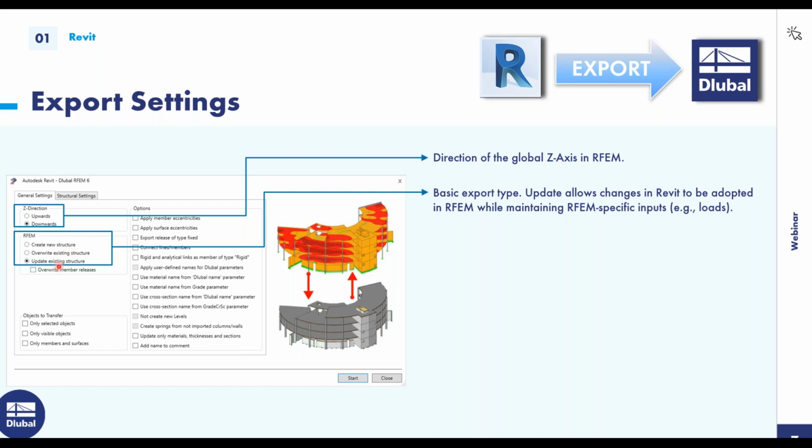And lastly, we have update existing structure, and this will just update the items or the objects that you've changed in Revit and RFM. So for example, let's say you first export from Revit to RFM, and then you modify the structure in RFM, and then maybe at some point the Revit model gets updated. With this update existing structure option, you can simply update the RFM model, and there's no need to start all over in RFM, and then you can save that.